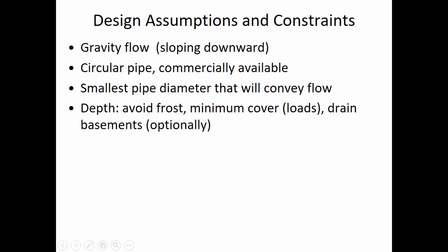And if the velocity is low, it settles to the bottom of the pipe. And so sediment can accumulate, and it's not self-cleansing. And so trying to have the smallest pipe diameter possible that will meet the standard helps to promote self-cleansing, rather than a pipe that has a lot of trash and debris and sludge accumulating at the bottom of the pipe and then needs more maintenance.